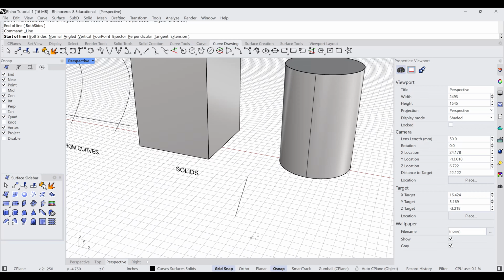So I'm going to go back to my line tool. I'm going to have grid snap, which we saw. It's going to snap. So what if I know I want this line to go perpendicular to the C plane? I can turn on ortho and I can snap, and it will automatically see the guidelines automatically forcing it straight up. Or I can go straight down, or to the left, to the right, and front and back. Now I'm snapping to the grid also, but this is also snapping perpendicular. So we can organize that geometry by using these tools.